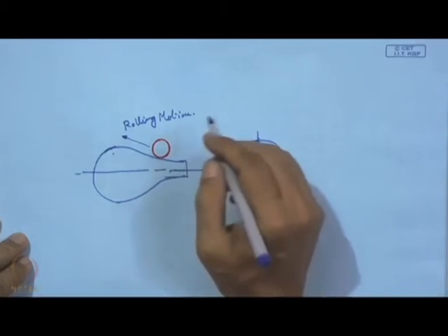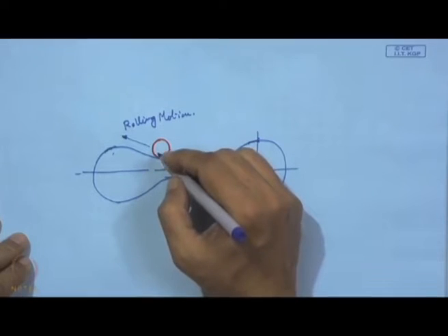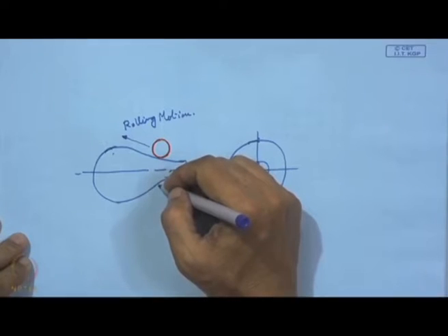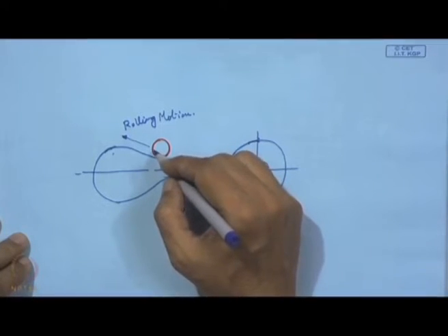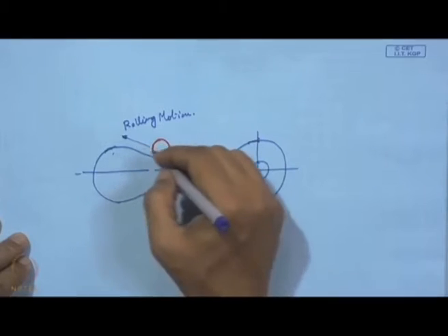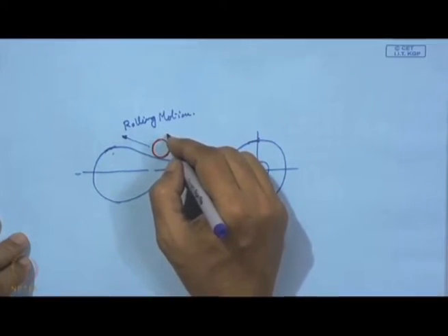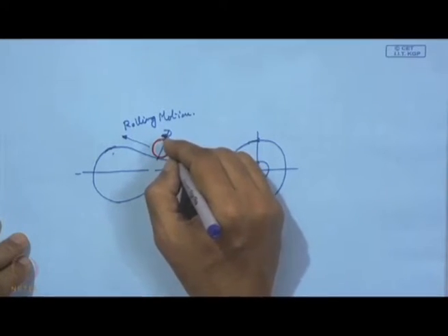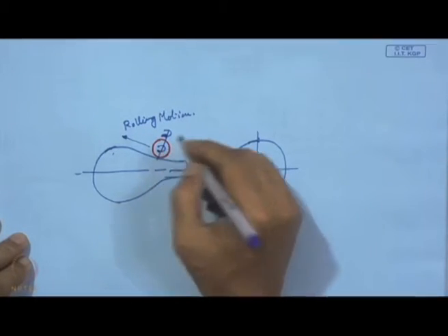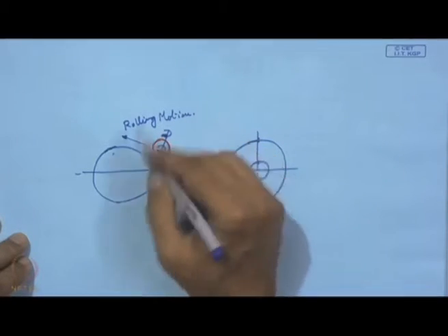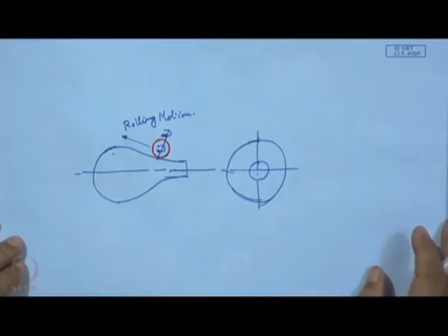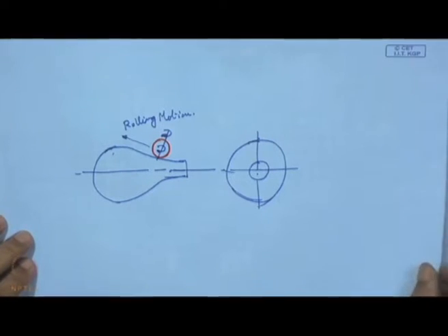So, it has two rolling motions, one about the axis following one particular diameter, and another following this contour. One is about this axis and another is about this axis. With that we can also have perfect ball burnishing over a contoured surface, which is going to be a 3D contoured surface.